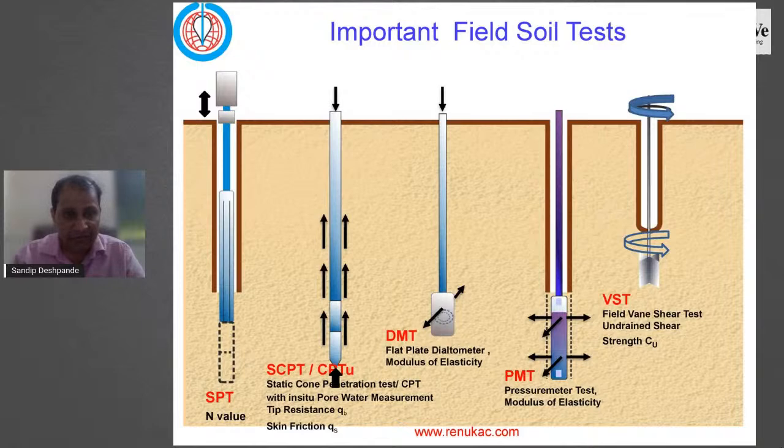These are the different kinds of field tests which are extensively carried out. The SPT test, as elaborated previously, is a simple driven tube at the end of the standard drill string, which is impacted through a standard weight, through a standard drop. There are, of course, energy computations to ensure that the energy imparted to the split spoon sampler is within the permissible limit and can be utilized.